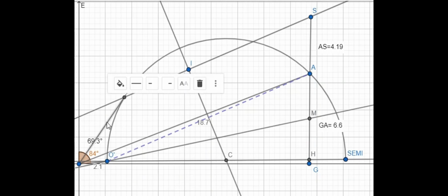The line OP is the phase current, and the angle EOP will be the phi angle. So for getting the power factor, we just take cos of the angle POE.